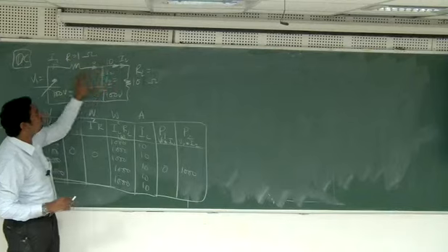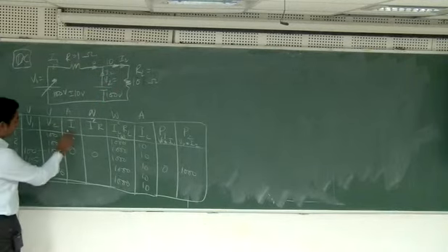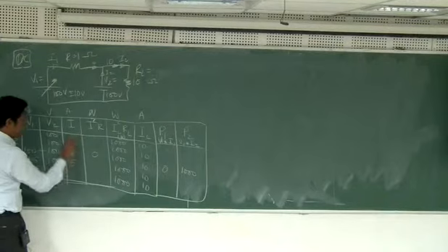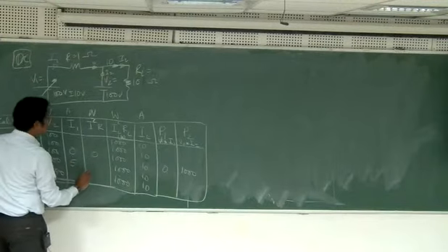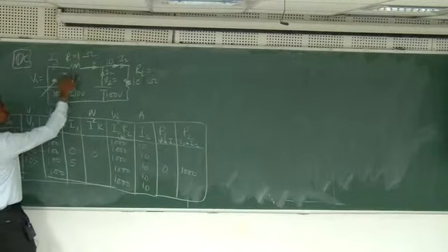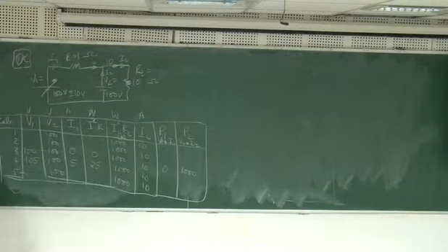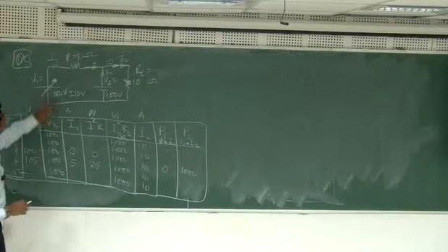So out of 10 amperes, 5 is coming from here and 5 from here. So what is I? I is 5 amperes. This is I1 actually. What is I1 square into R? 5 square into 1, 25 watts. Okay, 25 watts is lost as power. Therefore, what will be my V1 into I1? That is 100 into 5.